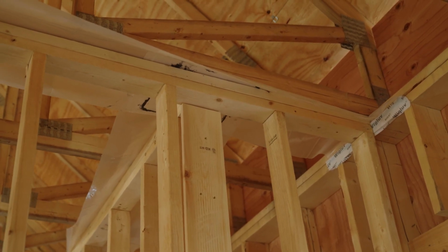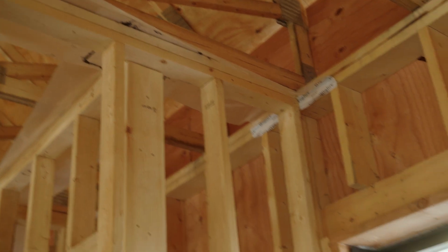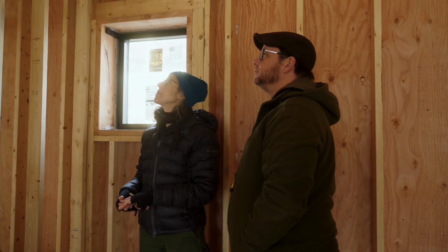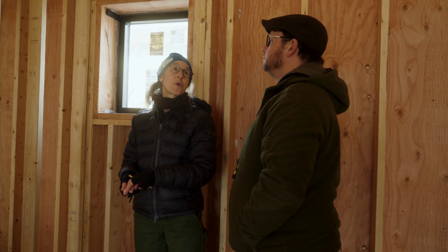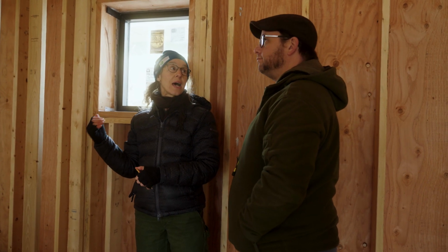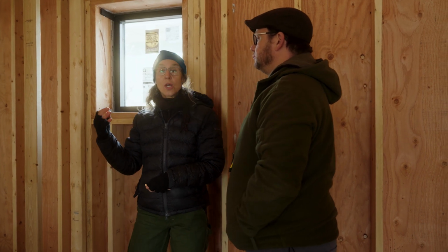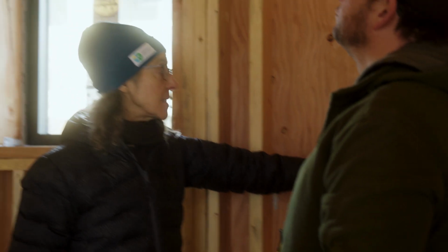I think an ideal example of integrated design at play, with the goal being superior air tightness in the end and durability of this air barrier. We really wrestled with the decision of whether or not to use polyethylene at the ceiling plane. We've seen an awful lot of builders of high-performance homes go with a rigid air barrier at the ceiling. Of course, we went with a rigid air barrier in our framed wall, which is this plywood.